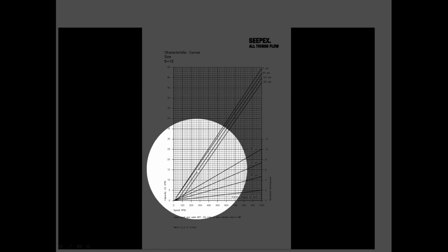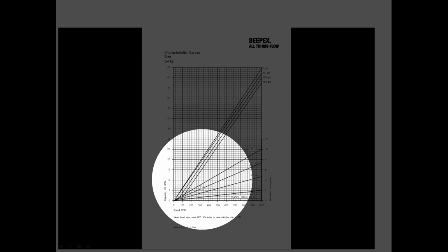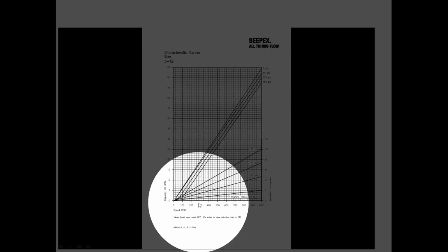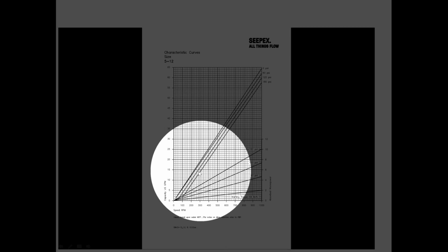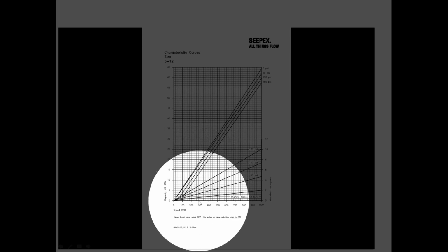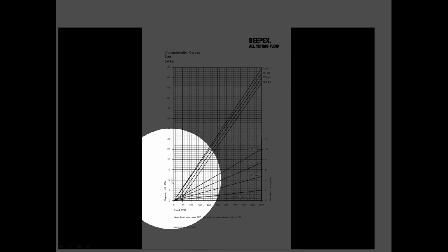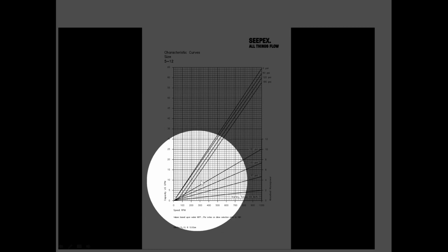With that being said, you know when your pump is getting tired, and you can proactively do maintenance on it. Because if you can see that, let's say at 300 RPM, you always had 15 gallons a minute, well, one day you come out and you check and at 300 RPM, you're only getting 10 gallons a minute. Well then you know that probably your pump is starting to wear a little bit and it's now time to do some proactive maintenance on it.